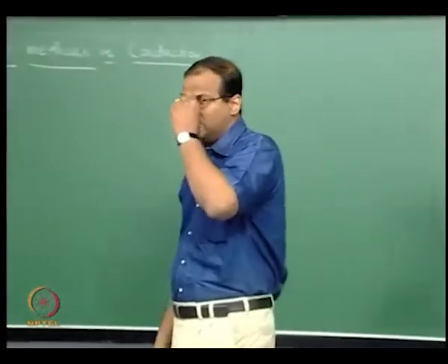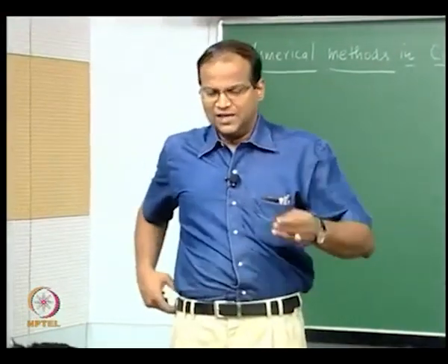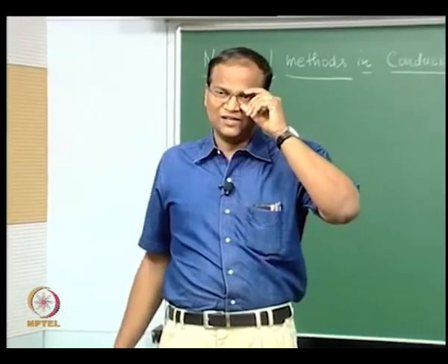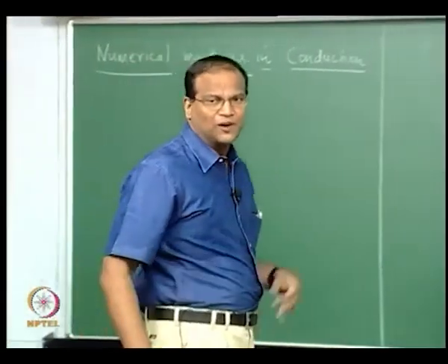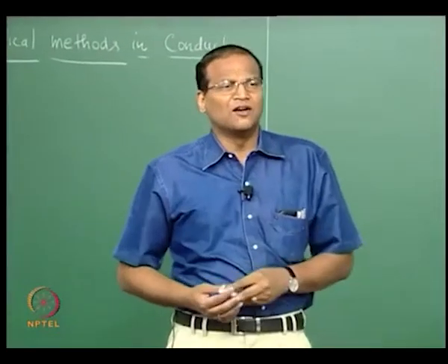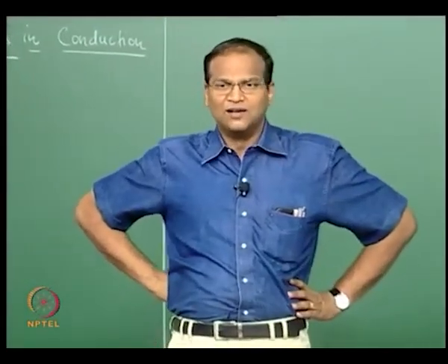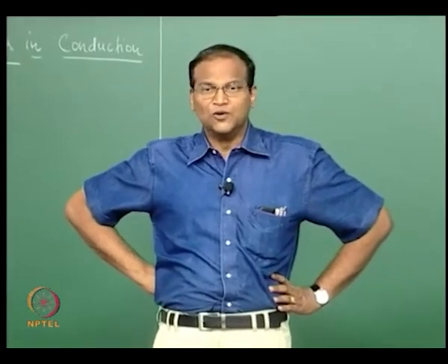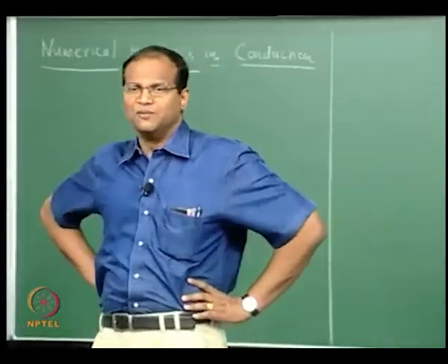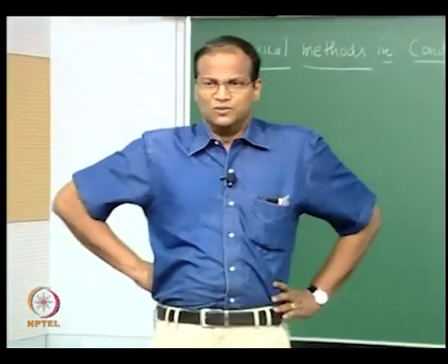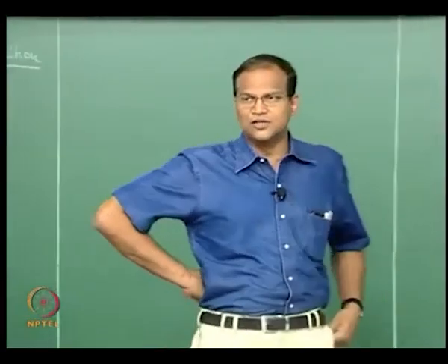Okay, but now you can see that even for a 2-dimensional, steady state conduction problem in a slab with constant properties, getting the analytical solution was quite involved, and then finally you have to evaluate a series. It is not that you got an expression like e to the power of minus mx, so you have to evaluate a series, and the accuracy of your solution depends on the number of terms you retain in the series. So it is not very convenient, though we claim that it is an analytical solution.